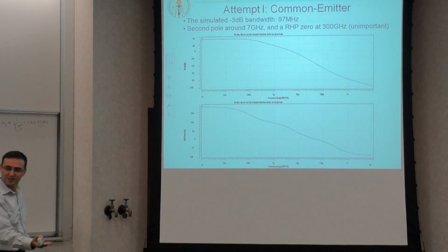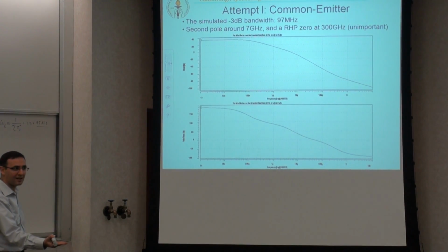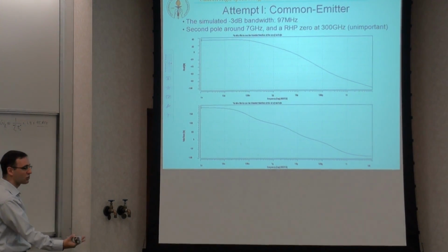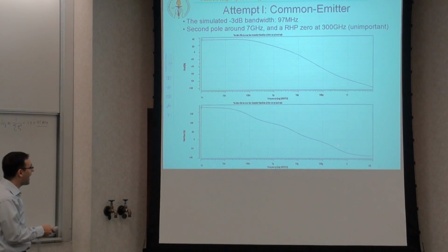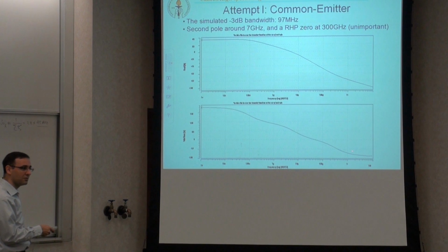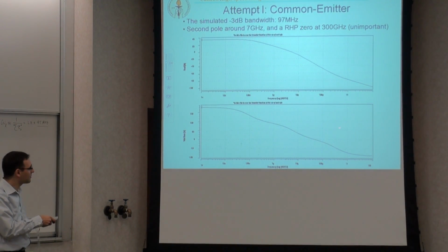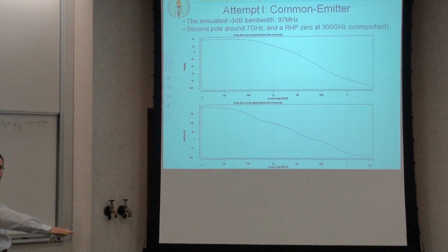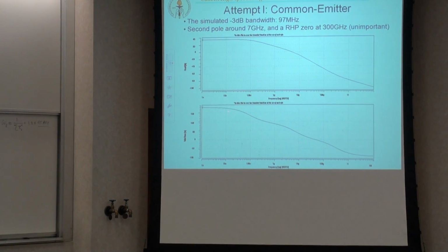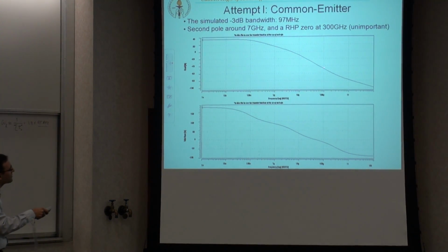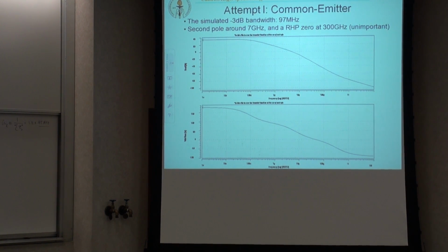You have 1 0, bringing it back to 20 dB per decade, cancelling the drop rate of one of the poles. And you can see it's a right half plane 0, because if it were a left half plane 0, the phase should come back up. It's a right half plane 0 because it's dropping again. So you have 3 drops in the phase, 2 because of the poles and 1 because of the 0, and 2 drops in amplitude and 1 increase, so it's very consistent with what you expect. Completely consistent.